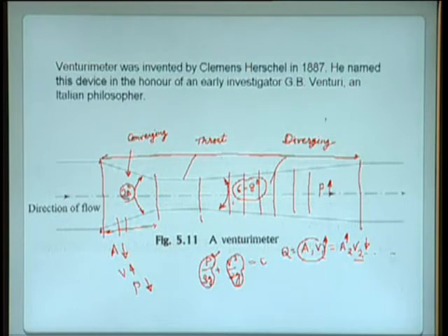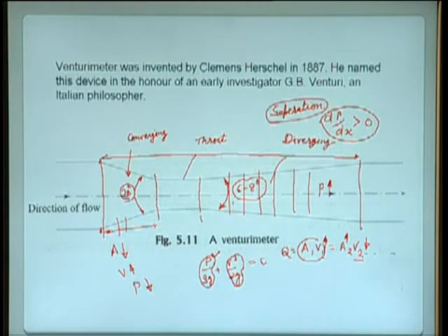Separation always happens when dP over dx is greater than 0, or positive. Only when dP over dx is positive do we have the possibility of separation. And whenever we have separation, which means rolling back of fluid particles, a large amount of energy is lost.